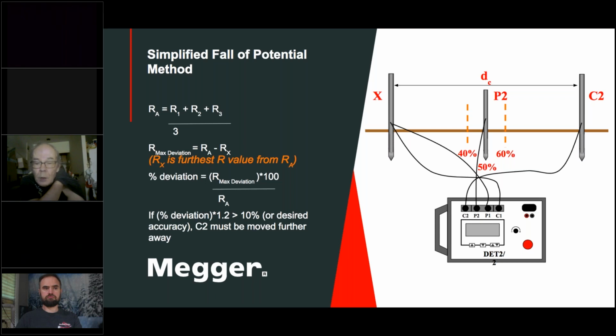So, okay, what's an open? Well, the way a Clampon worked, the Clampon tester, you're holding it in your hand and you clamp the jaws over the top of the ground rod and you've energized it. What it's doing now is it's establishing a high frequency test current inductively from the rod through the soil, and then it finds its own return.